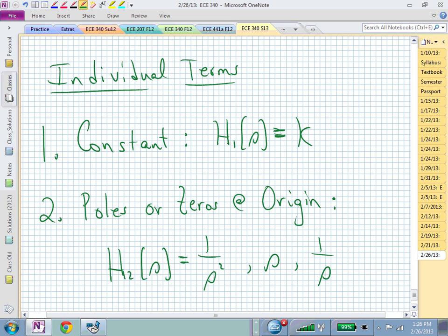If somebody says an integrator, do you remember your op-amp circuit to realize an integrator? You have a resistor and then a feedback path which includes a capacitor, where that feedback path goes back to the inverting input of your op-amp. This 1 over s in the frequency domain is in the time domain really just an integrator.